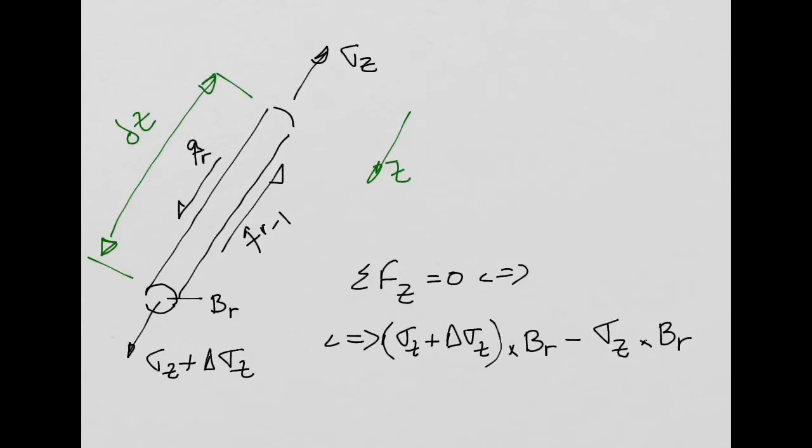But I have also the shear flows. I need to include the contribution of the shear flow. So plus, I will continue here below. Let's now add the contribution of the shear flows. Let's start with this one here. This shear flow, QR, is a force per unit length, don't forget. So I need to multiply this QR by dz, right?